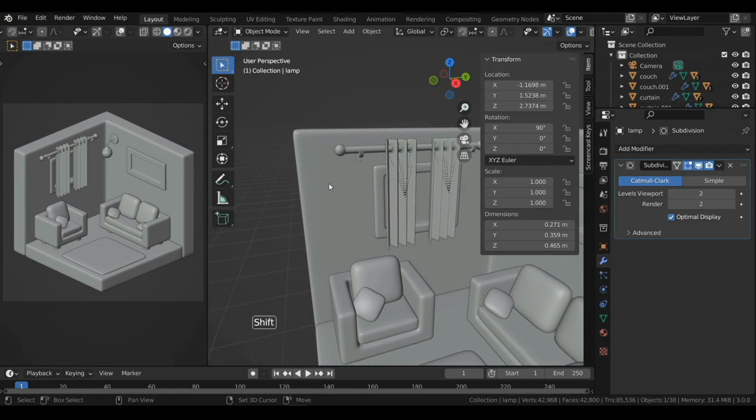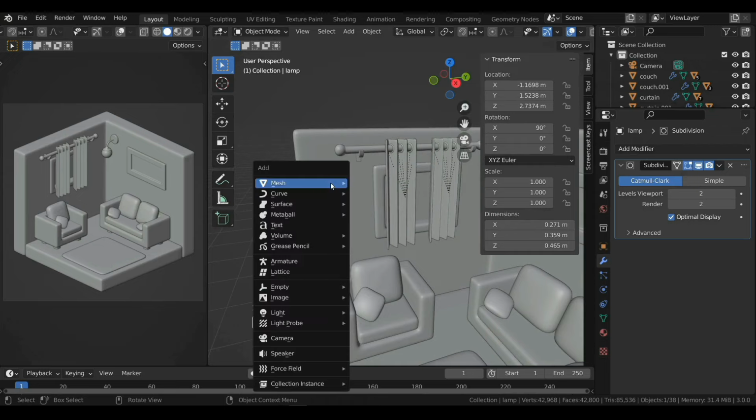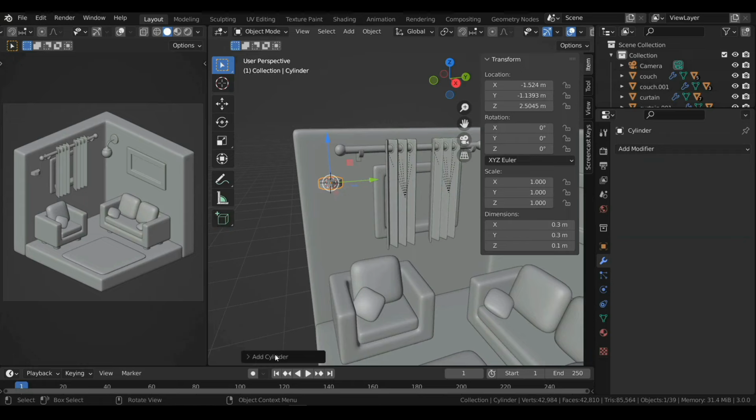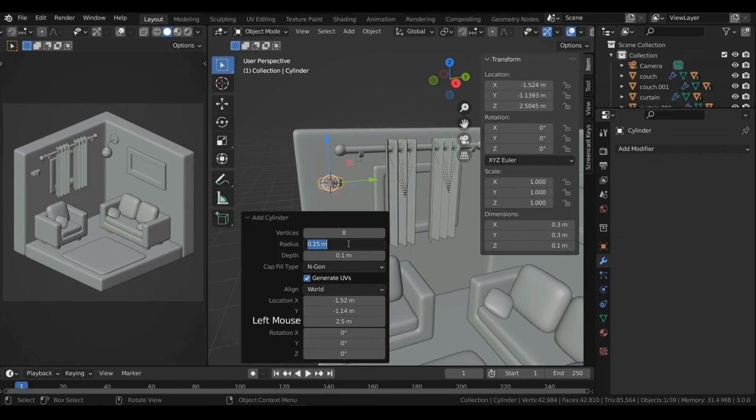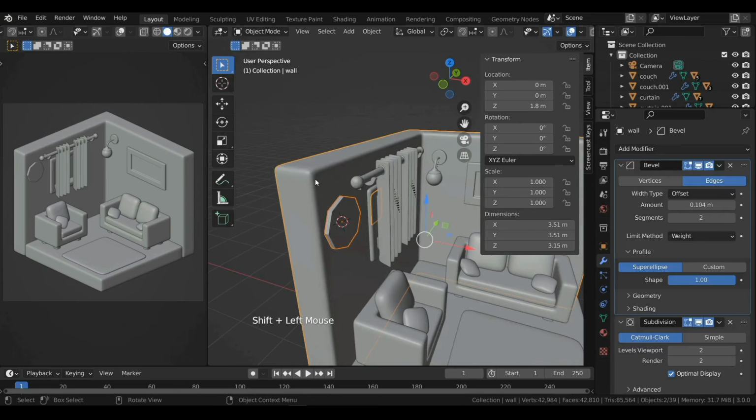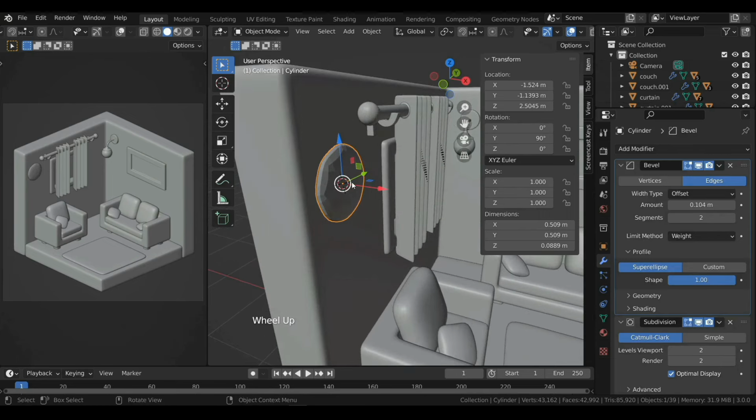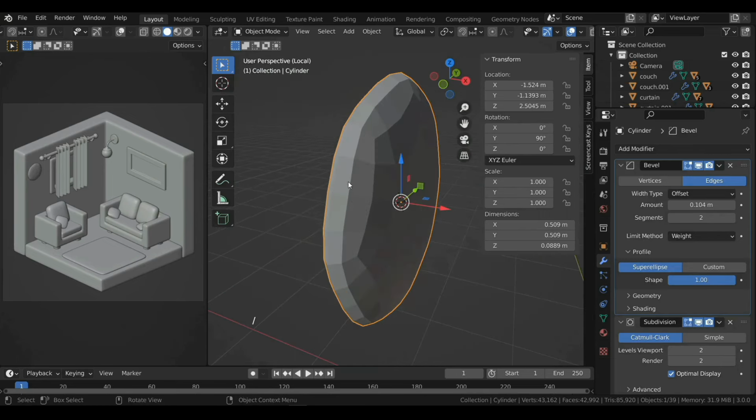Place the 3D cursor over here with Shift right-clicking, and add a cylinder with 8 vertices. 0.3 radius, and rotate it 90 degrees on the Y-axis. Then Shift-select the wall, press Ctrl+L, and select Copy Modifiers. Then with the clock selected, press / to isolate it.